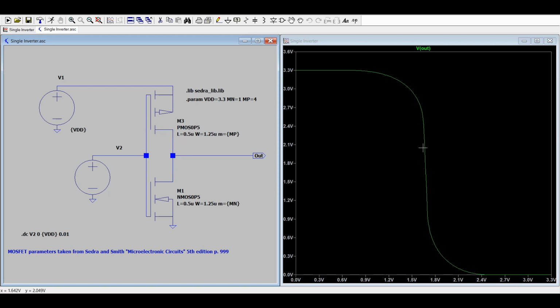The way we explain this diagram is exactly in terms of these FETs being voltage-controlled resistors. As the input voltage here begins to rise, once we've passed the threshold anyway, this channel is going to start to open up and allow electrons to flow, and this channel starts to close, restricting the flow of holes there. So we've got one resistor here, the other resistor here, the output is given by this voltage divider. And so we get this nice transitional curve here.